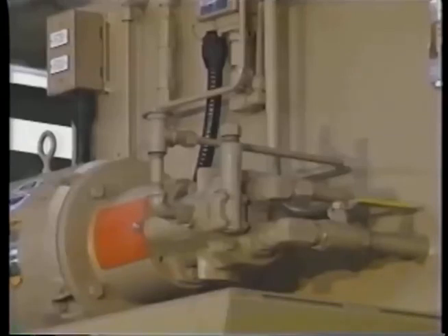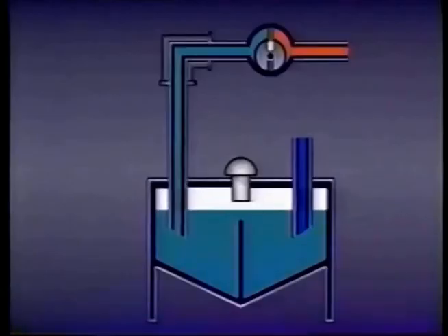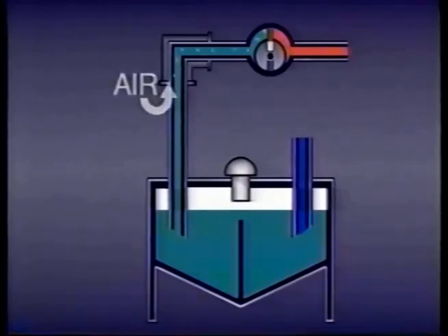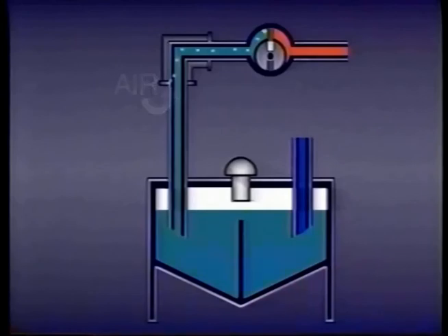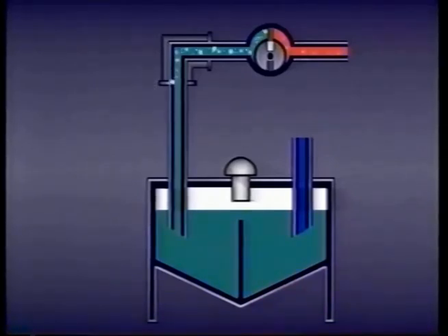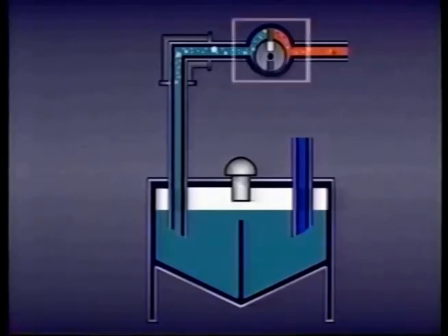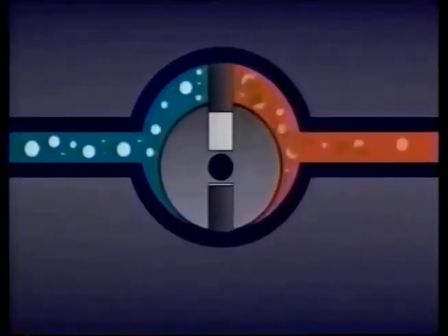However, oxidation inhibitors have little effect when oxidation occurs at the outlet side of a hydraulic pump. Oxidation in the pump happens when air is allowed to enter the suction line through a leak or by excessive churning of the oil in the reservoir. In either case, the air forms bubbles which collapse when they are subjected to the high pressure at the pump outlet. This not only oxidizes the oil, but the collapsing bubbles create extremely high temperatures, which can actually fry the